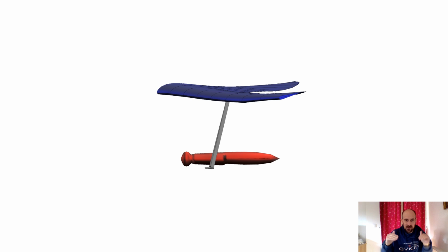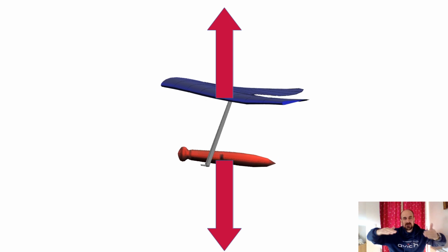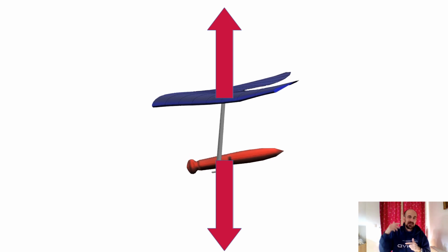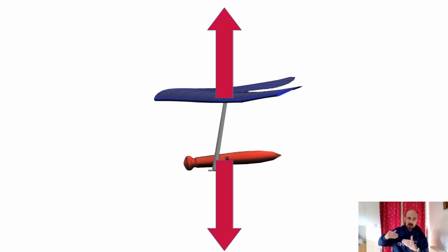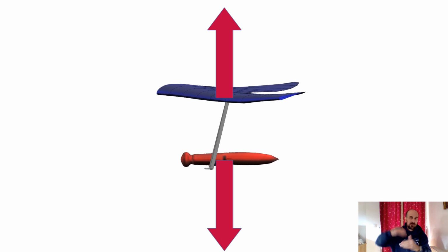When they're in steady state flight, the amount of lift must always equal the amount of weight. And because of the stability we talked about earlier, if you accelerate to a different speed, whatever steady state condition you're in, lift is always going to equal weight. So you always have to be generating lift. What we're looking for is the way to generate the most lift while generating the least drag. If we generate more lift, the glider is going to fly at a lower angle of attack. So it's about improving that ratio of lift to drag.